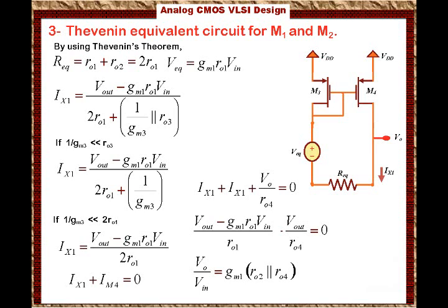Remember, the objective of the op-amp design as an amplifier is to design an amplifier with high gain such that when we use the feedback, we will be able to tolerate the approximation and come up with accurate gain. So the idea in analog design when you design an amplifier is not to be exact as much as to be approximated, such that when you use the feedback you will come up with accurate gain. And that's the whole concept behind analog amplifier design.